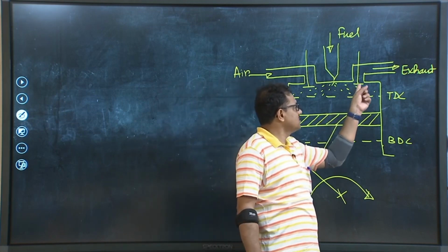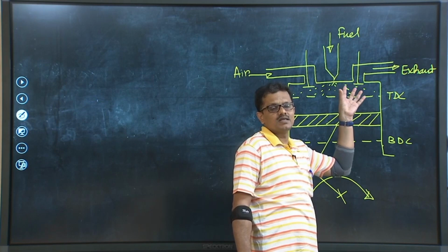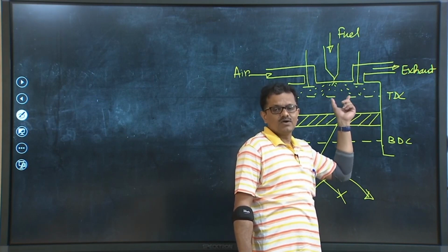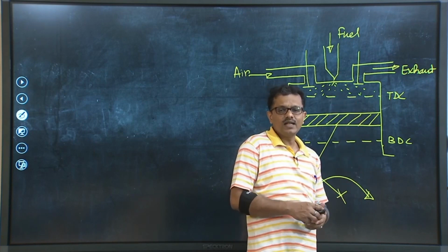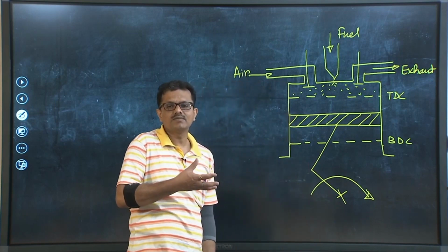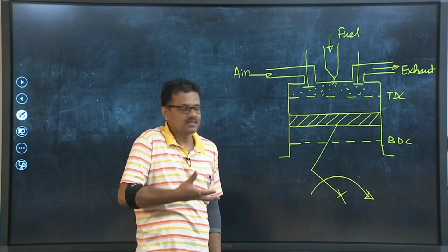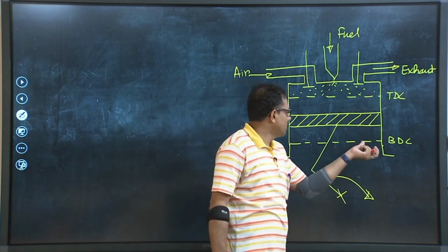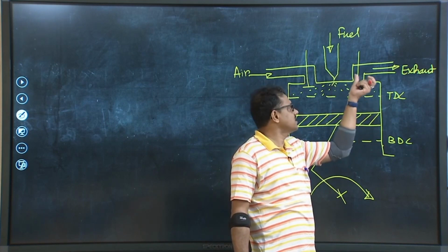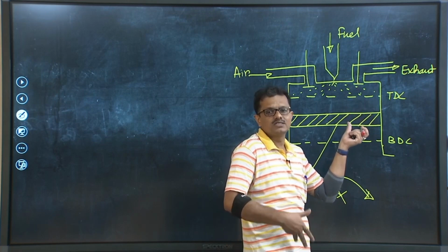When the exhaust valve is allowed to open, a certain amount of combustion gases will leave the cylinder, and while leaving, those gases will carry a certain amount of energy. It is called blowdown or heat rejection. And finally, when the piston is again travelling back from BDC to TDC, the intake valve remains closed but the exhaust valve is now fully open. That is called the exhaust stroke.